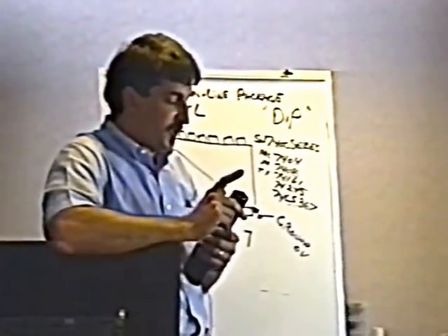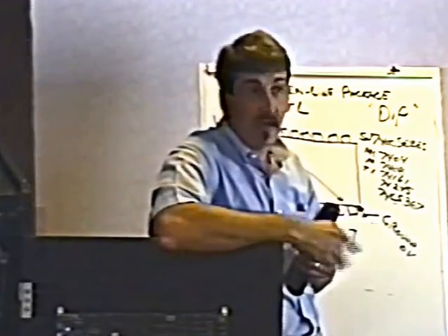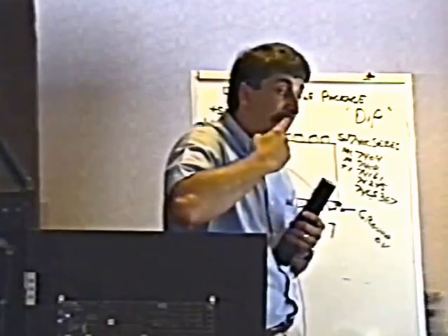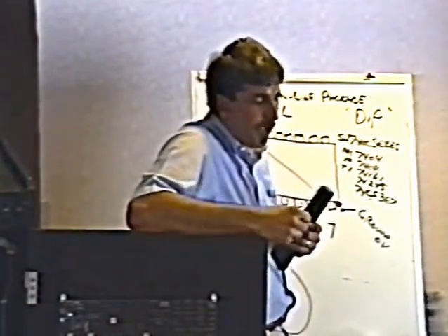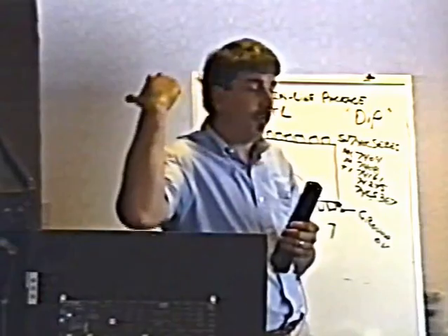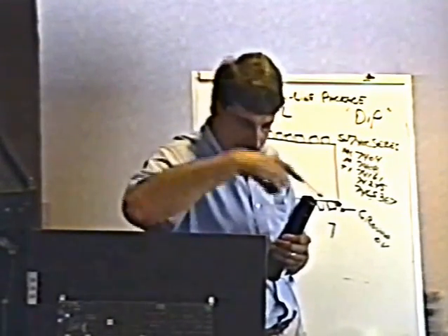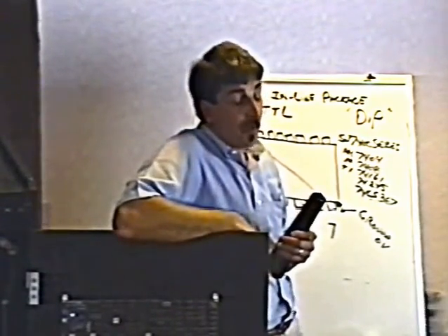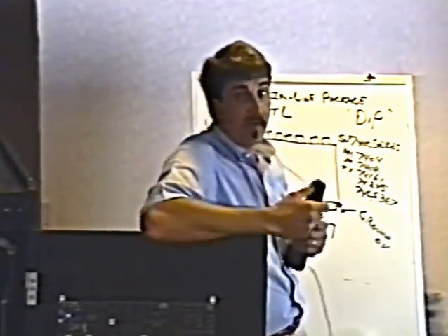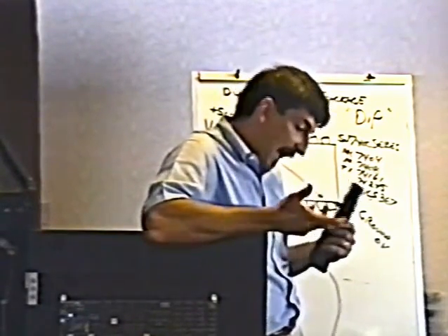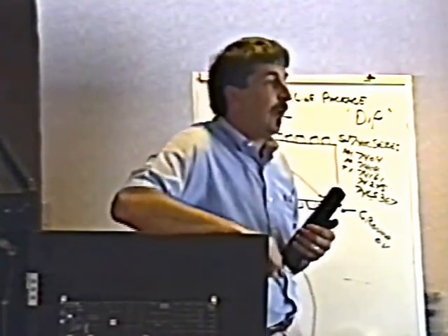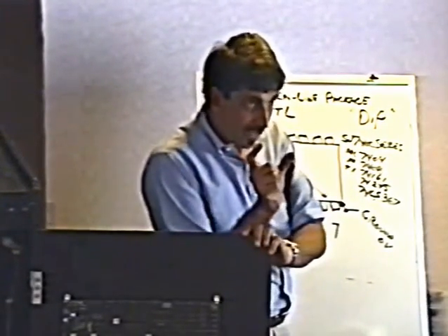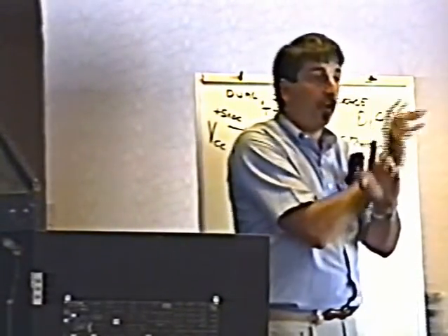I always tell my boss, never get just one of anything. Never get one of any game. Because if you only have one, I can't do that anymore. But for instance, we had an Outrun problem. And we just saw garbage on the screen, like this garbage, almost exactly the same. But it did pass the whole ROM check. I don't know how or why, but it did. So I took the bad boards and I drove 20 miles over to a location where we had another Outrun, and I sat down behind the Outrun, and one at a time I took the integrated circuits from the bad board and swapped them with the good working board.